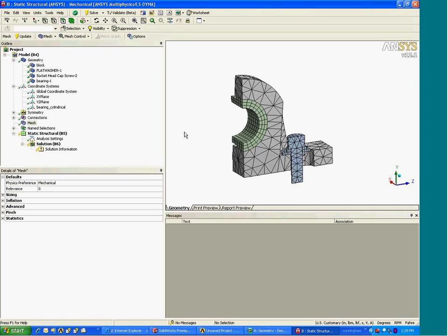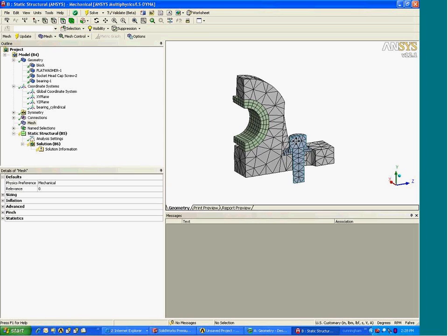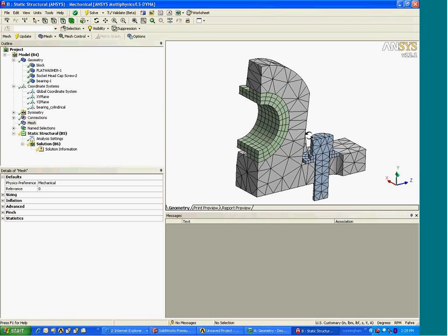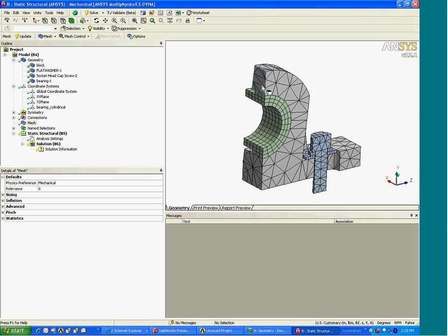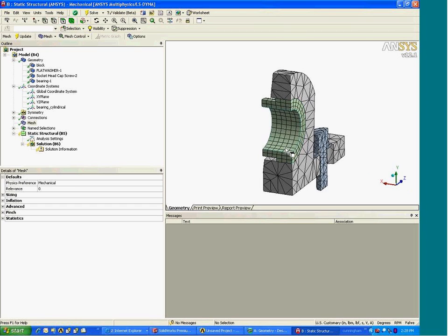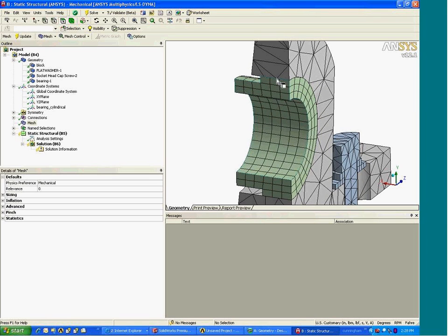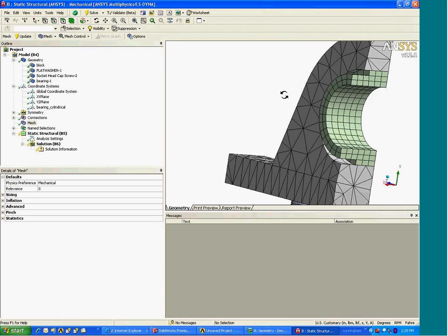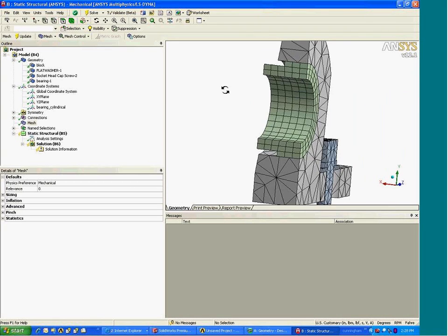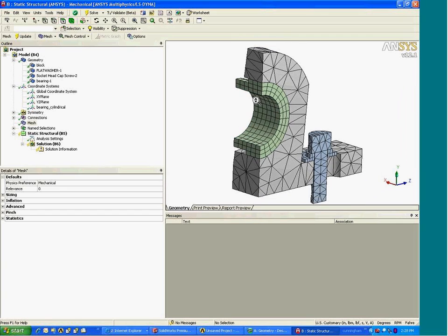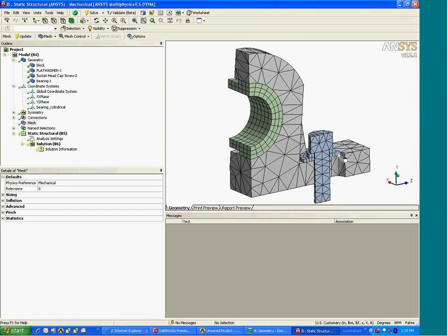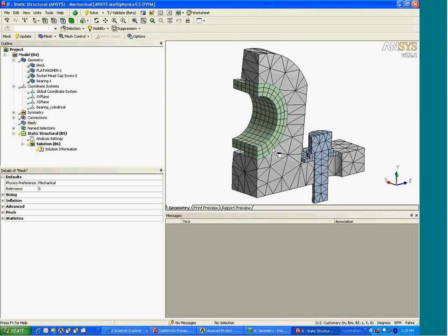with that, go back and start to apply more local or specified mesh controls in regions where you expect to get sensitivity to stress. So in my case, I know I'm going to be looking at the hoop stress in and around the bearing, so I'd like to get a little bit more resolution in the block. You'll also notice here that the bearing, although it was not a general shaped item, was automatically hex mesh. So there is some intelligence built into this ANSYS mesher that will mesh bodies like the bearing and also the washer with a fully brick mesh if it can.